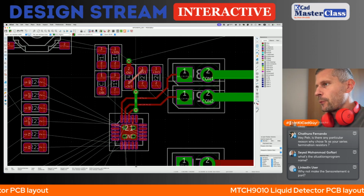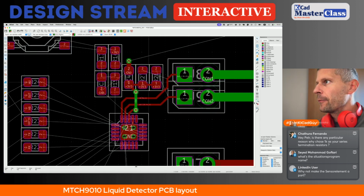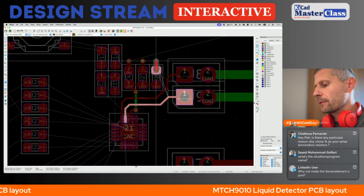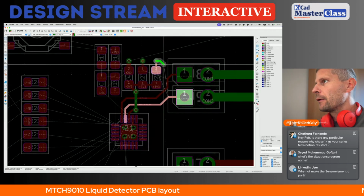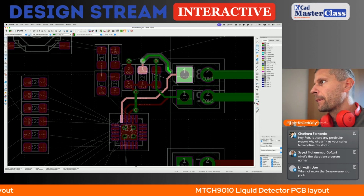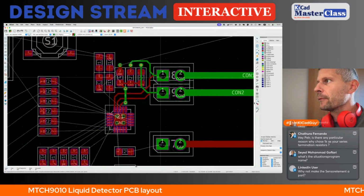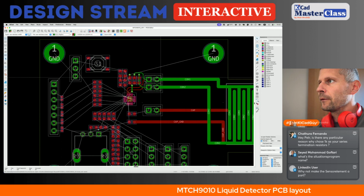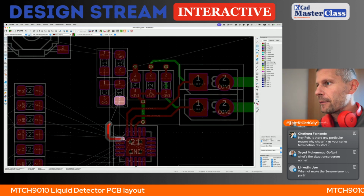No, do you want how I resolve this issue? I will rotate these two pull-up resistors and use two vias and connect them on the bottom layer, because the jumper is obviously THD. Here. Okay. Here is the reset circuitry.